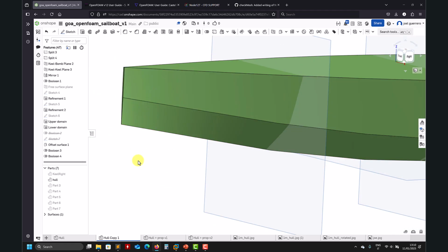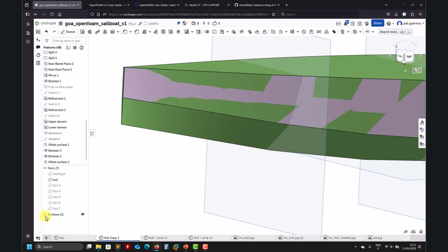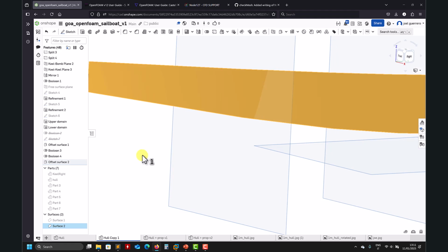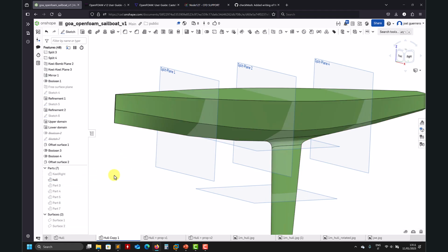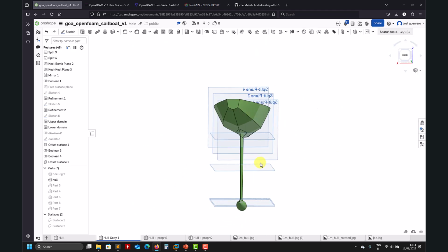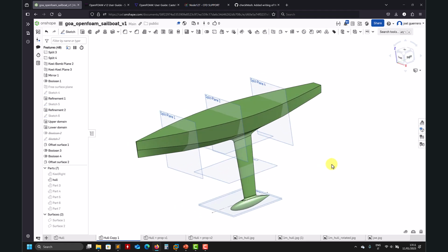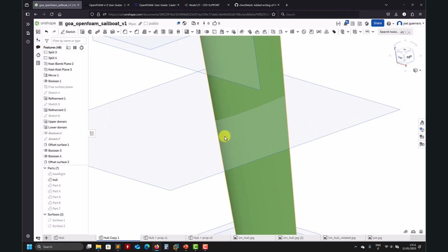Just spend some time, as I say, now you can understand a lot of things, your distance and everything. Also, as I mentioned here, we're going to need these faces. So see that, select this face, you have this option offset by 0, and now that says face is here. You can export it as STL, and when you export it and you use surface features, now you're going to properly capture all these edges that previously, if you use the whole geometry, like in this case, it's difficult to capture. Okay, so it's up to you to select. In my case, I selected all surfaces. Now later, I did some other operation, we're going to see now that, for instance, the leading edge, I created another surface just to add the region refinement there and so on.